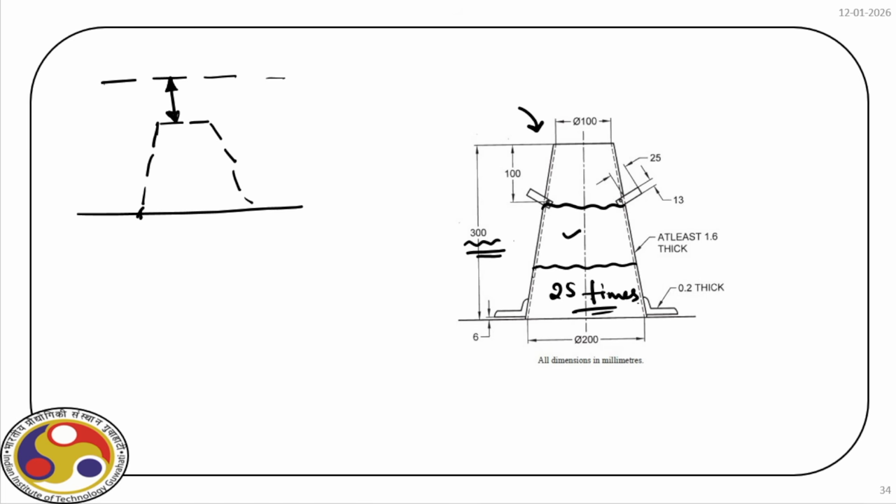Sometimes, the moment you remove the cone, the concrete can form a bulge. Sometimes it can have different types of failure, like this one, which is called shear slump. In that case, the middle height of the shear slump face is considered the height measured in the slump test.